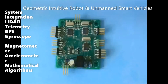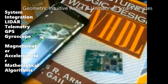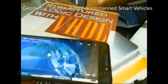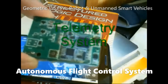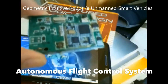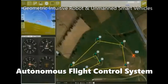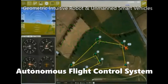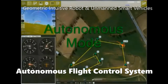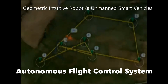I also integrated a telemetry radio and airspeed sensor system. The telemetry radio connects the autopilot system to a laptop computer so you can monitor the drone. In an autonomous mode, the autopilot controls the servos. Inputs from the RC transmitter can override the autopilot.